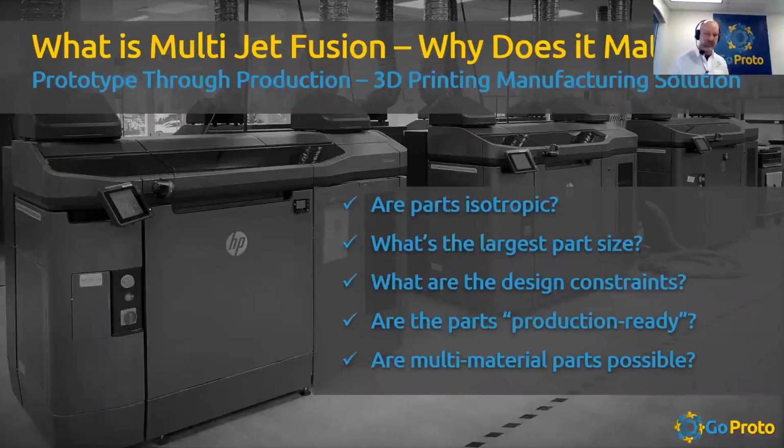There has not been a great solution for elastomer 3D printed parts in the market to date. There's been essentially fused deposition modeling, or FDM, that has had a TPU material. There was a material in selective laser sintering that was an elastomer that was okay, but kind of crumbly and didn't perform well in terms of isotropic properties. And there's been some DLP technologies, as well as, like, say, Objet, that those materials are photopolymer approximations of elastomer. And they leave some things to be desired.